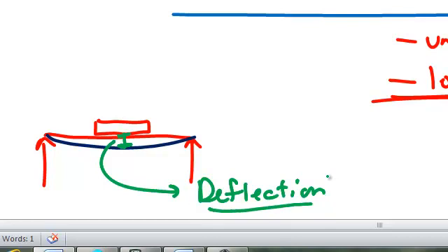Now, a beam technically could deflect a lot and not have any structural problems. Especially a large beam carrying a heavy load, it could sag 4 or 5 inches if it was a long enough span and really not have any structural issues. It would not fail for shear, would not fail for bending stress. It would be just fine.